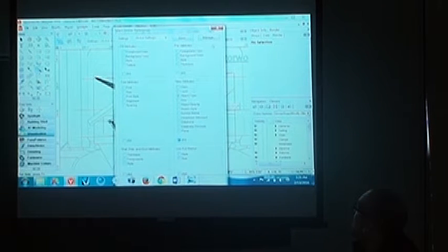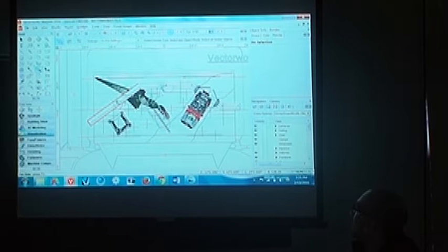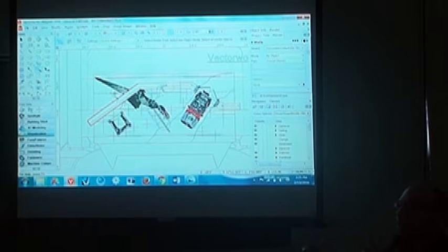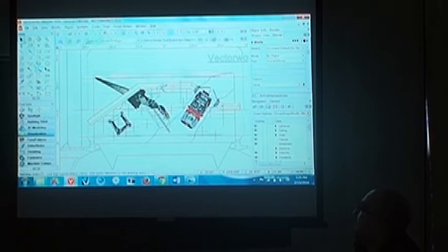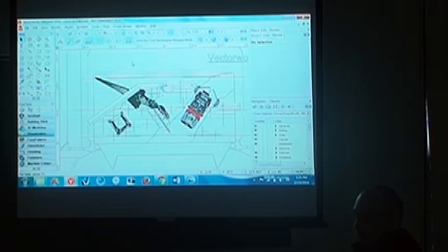It allows you to select objects based on things that they have in common with each other. Like right now it's set to object type. So if I select something, it's going to immediately select all the objects of that type. So I just got all the walls in my drawing here that are visible with one click. So that's a really handy tool, especially if you have a drawing or a model that you didn't pay any attention to the organization when you were creating it, the layers and classes.